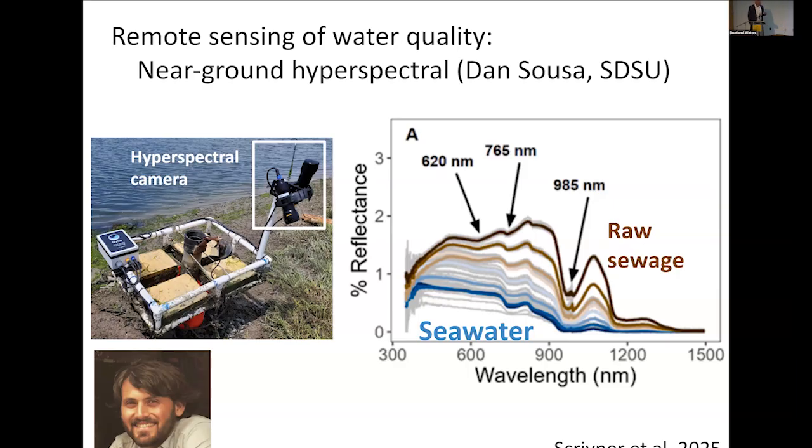And we've documented that satellites can see these same wavelengths of light, which can allow us to map the sewage and detect wastewater with a camera. This camera is mounted in the Tijuana estuary. It's collecting data today, along with one of our fluorescent sensors. We're working to correlate the measurements in the water with the camera and the satellite, so we can map changes in water quality without having to go to the field to collect a sample.